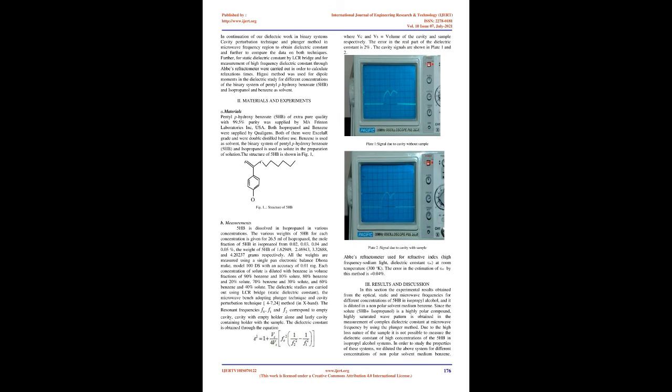Birnbaum et al. 14 observed that the microwave resonance method is used to determine the dielectric constant and loss of liquids, solids, and very lossy gases, provided the cavity volume is only partly filled with absorbing dielectric. A microwave resonance technique suited for measurement on low-loss liquids has been described by Pitt and Smith 15.